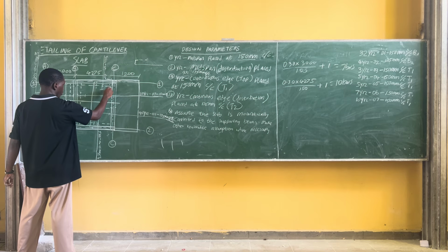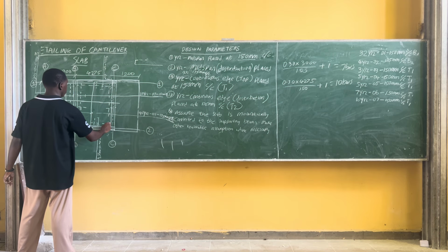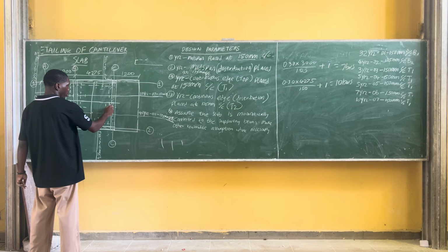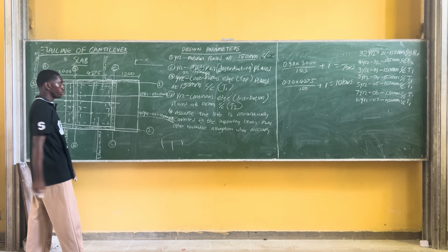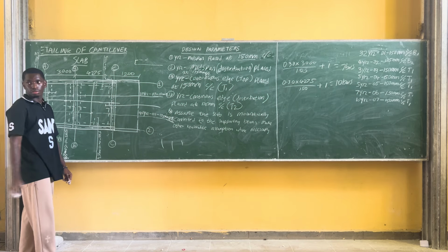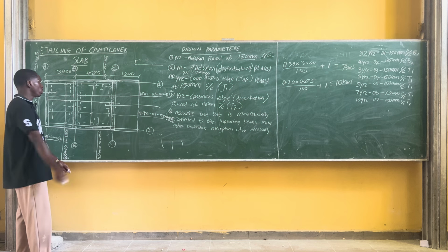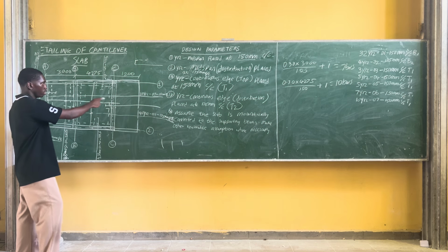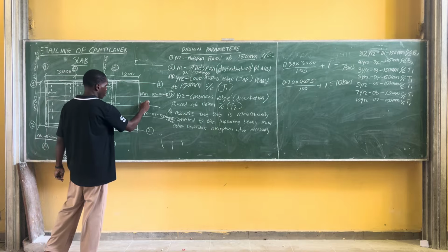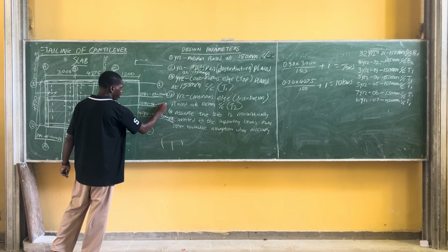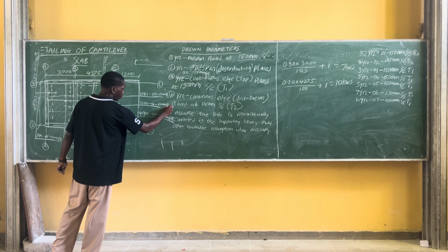So I'll draw my reinforcement, which is still the same thing. This reinforcement is spanning from here to here, which is 0.3 times our 4275. You understand? Which is giving us 10 y12 bar mark 08 at 150 mm center to center T1.